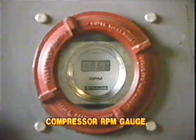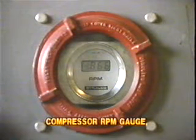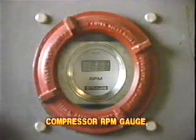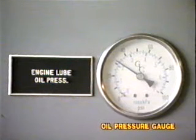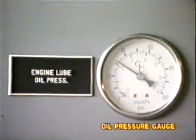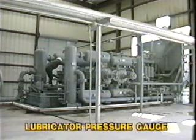The compressor RPM gauge indicates the crankshaft speed in revolutions per minute, or the relative speed of the piston's movement within the cylinder. The speed should remain constant, as set by the speed control settings for the compressor package. The oil pressure gauge shows the pressure of the oil supplied to the bearings. Normally, this is within 20 to 40 psi. The lubricator pressure gauge gives you the pressure of the lubricant supply to the cylinders and packing.